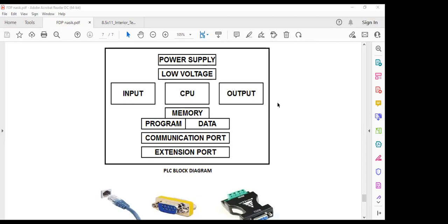I will have to do it fast because programming is also a lengthy topic which will take time. So, another example of high speed output. In college, we use one motor, stepper, correct. Stepper motor you know. Stepper motor will not run by just on-off. It's not like you give it 24 volt DC or 230 volt and it will start running like an induction motor. No. This requires a number of pulses.